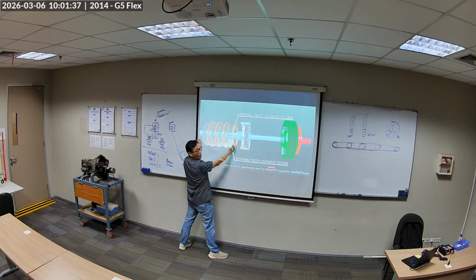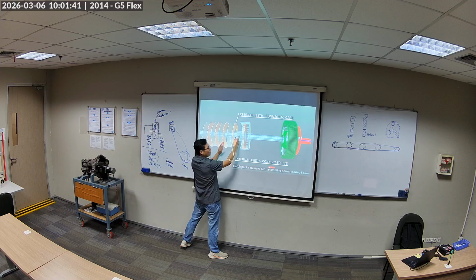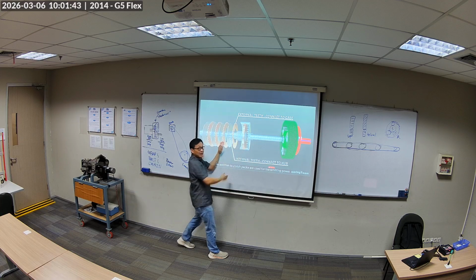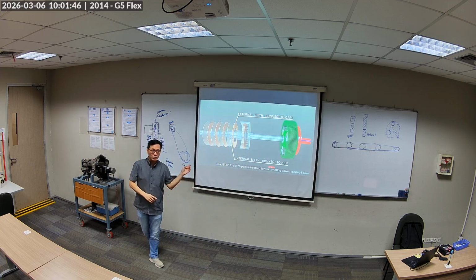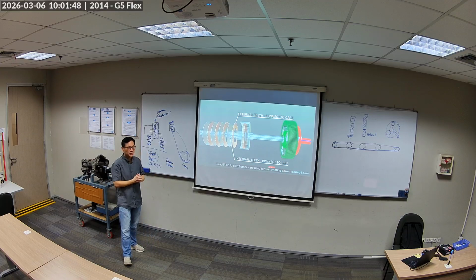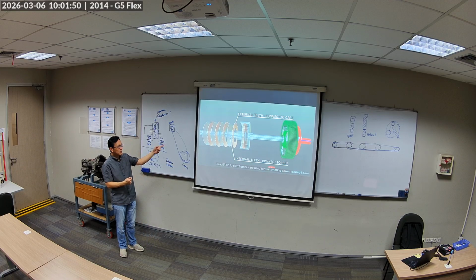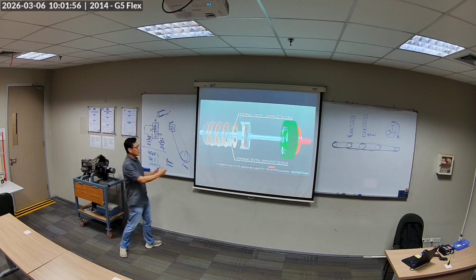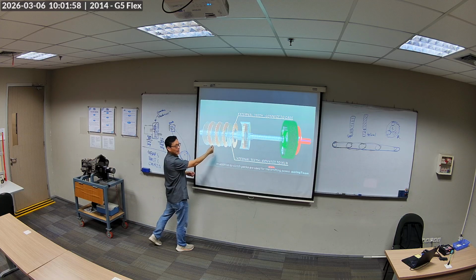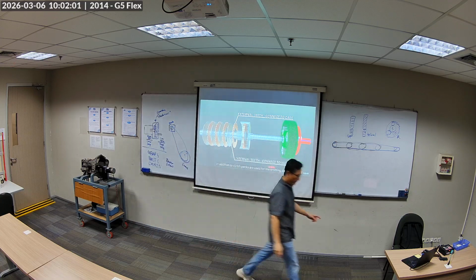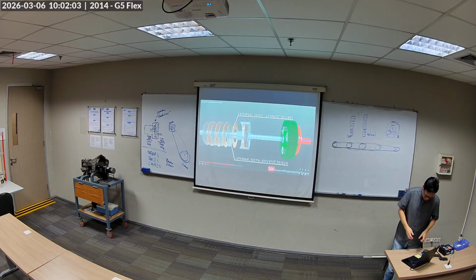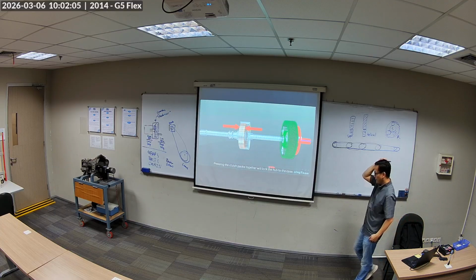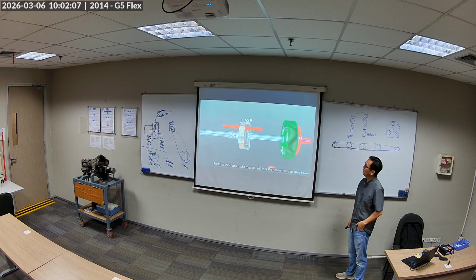But when I put oil pressure and clamp them together, that's how I join the shaft and the hub. Okay? This is actually typical in motorcycles, wet clutches. But the thing with this is I can control it with hydraulics rather than a mechanical motion of links. So this is hydraulically clamped. Pressing the clutch plates together will lock the hub to the case.